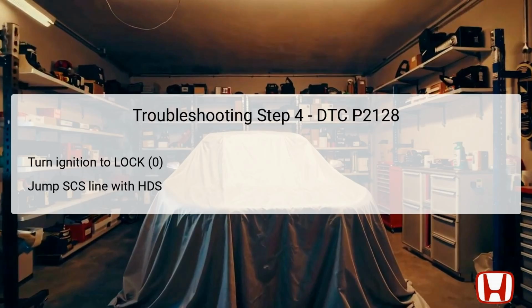Jumping the SCS line helps to avoid unintended airbag deployment during diagnostic procedures. It is imperative to handle this step with caution, as the SCS is directly related to the vehicle's safety features. Following this precaution, you can proceed to the next steps of the troubleshooting process with confidence that safety systems are not affected.